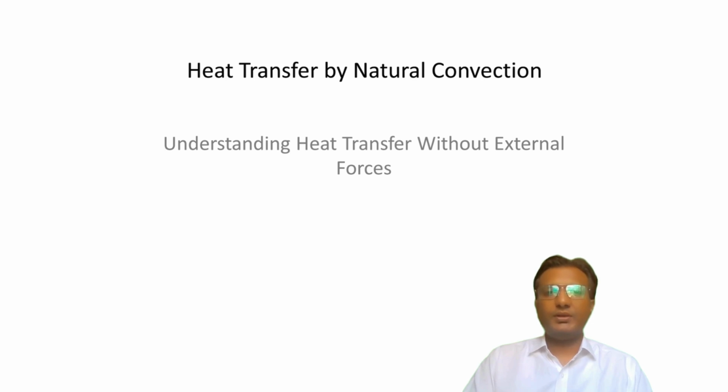Good morning, everyone. Today we are going to see natural convection heat transfer. It is a fascinating process driven by temperature-induced density differences without external forces like fans or pumps. Natural convection is key in applications ranging from home heating to atmospheric circulations. Unlike forced convection, which relies on mechanical devices, natural convection occurs spontaneously when a fluid is heated or cooled, creating fluid motion that transfers heat.